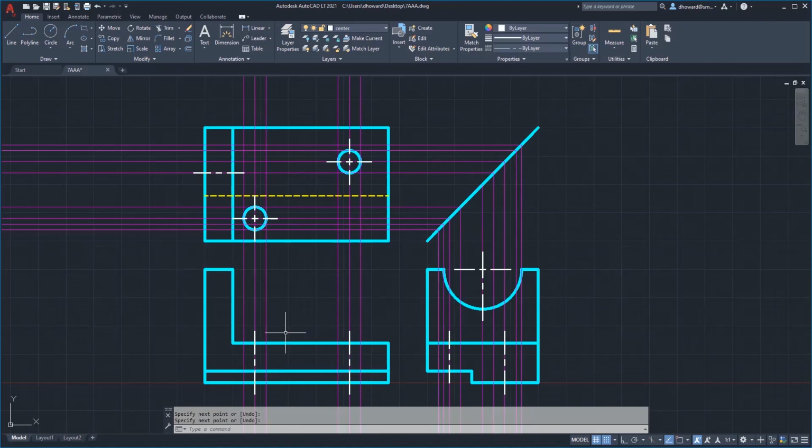In this view over here, again, you might be tempted to do something like this, but this just looks strange. It's just looking like the object line is extending out the top for some reason, and it's just going to be confusing. So that is not really a good place to put a center line. Although technically it is there, I'm not gonna do that because it's just confusing.